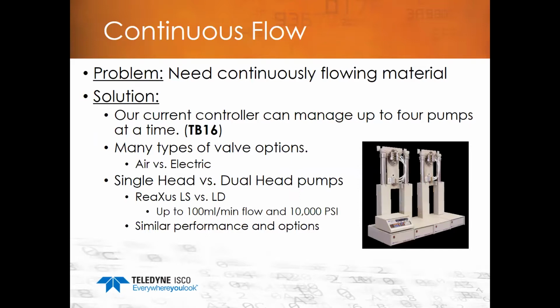which is pretty exciting in some cases for some folks. We do have a technical bulletin on our website that discusses all of that and how to set it up and how it acts. You can set it up so they're all in unison, so it goes piston 1, piston 2, piston 3, piston 4. You can do piston 2, piston 4, piston 1, piston 3, alternating. You can do 1 and 2, 3 and 4. There are many ways you can set them up to dose in material at specific times. So you can have 4 pumps potentially dosing in 2 different types of materials within different time settings, and you would set that up on the controller that comes with the product. Great opportunity, great flexibility we have in our pumps.